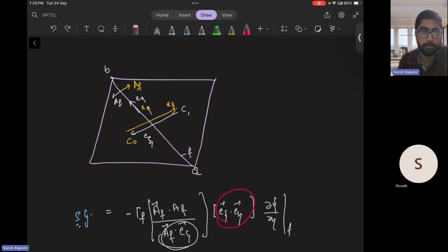So basically, what is the algorithm? We give the initial guess for phi at cell centroids and calculate the gradients at cell centroids using the gradient theorem. Coefficient calculations happen. We traverse through each and every phase from 1 to n phases, calculate A and B, and assign A and B to C0 and C1, sharing the common phase. Calculating the secondary gradient, it will come into the B terms: B0 equals B0 plus secondary gradient, and B1 equals B1 minus secondary gradient because of the flipping. Then traverse through each cell again for calculation of AP and B's. Solve the equation AP phi P equals summation of A and B phi plus B to obtain the new phi P's using the Gauss Seidel solution, and then check for convergence. If it is not converged, then go back to step number 2. Everything has been discussed by the prof in the lecture videos, so you can take that from there.